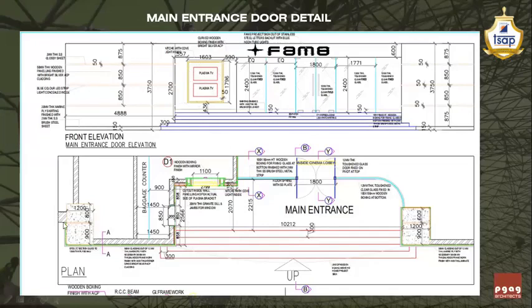Then the whole area, the external wall of the space, is going to get cladded with ACP paneling, which is a 50 mm thick paneling with ACP sheet finished as a finished surface. And then we have proposed 50 mm wide wooden molding with light element inside. In the next slide, I will show you the detail of the 50 mm thick molding, how we have done that.